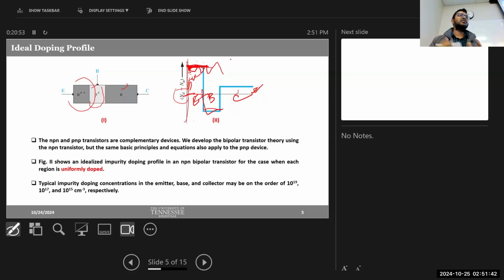And I think in this course you will also use the TCAD tool. You had one lecture on that, right? When you use that tool, you will be able to choose the doping type. You have Gaussian doping, you have uniform doping, all those different variants of doping. So you can do that in simulation, but in practical life, you have much less control over the type of doping you do.